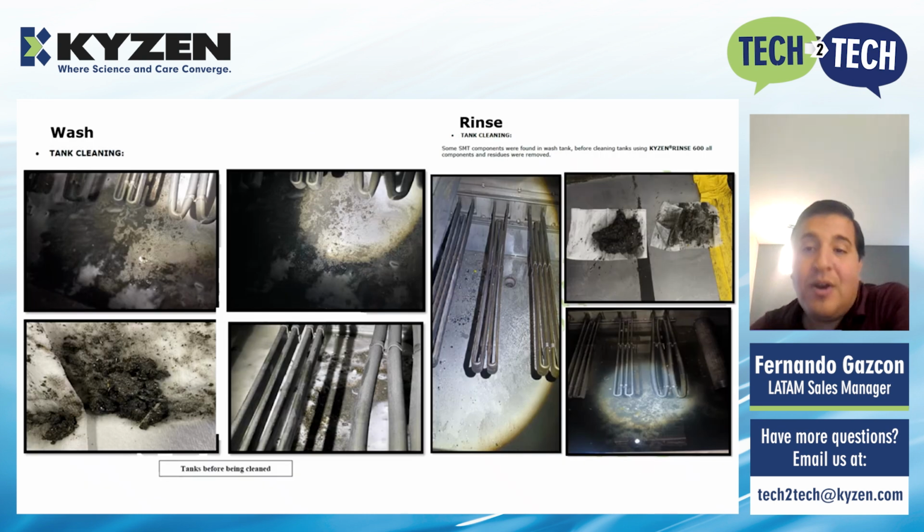We noticed there was a scale buildup on the tanks, the heaters, and even in the pump inlet filters. This scale buildup usually accumulates due to poor quality DI water used, or it could also come from the cleaning agent you are using in your process. Some chemicals tend to generate scale on your equipment. This is not something desired and should be avoided if possible.